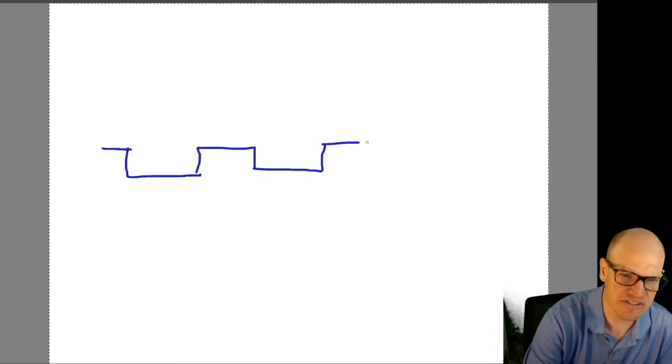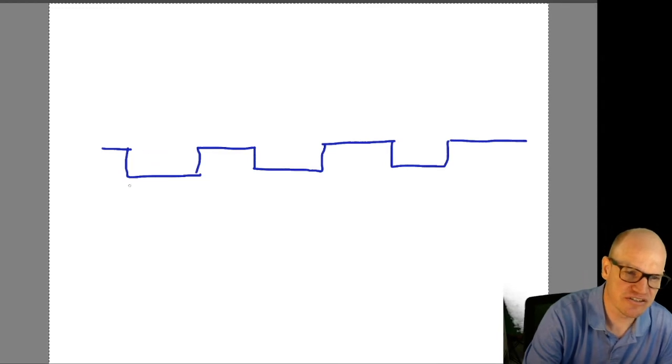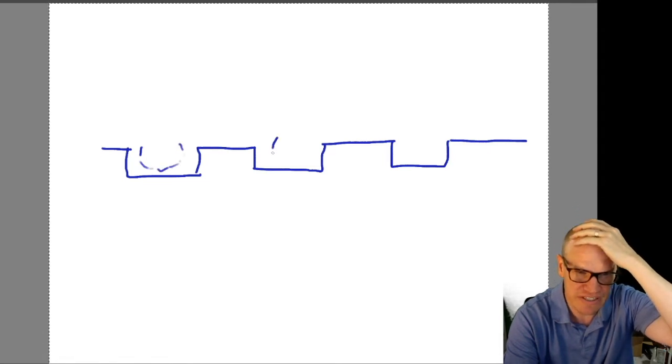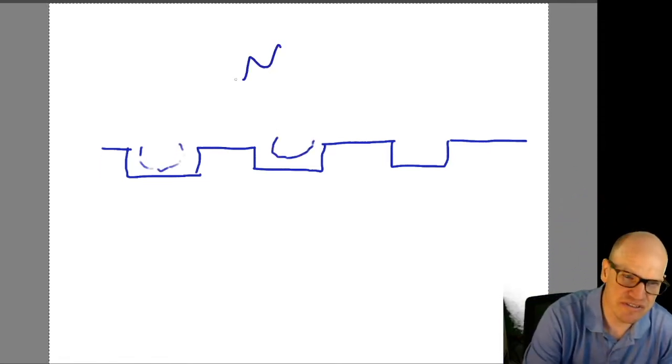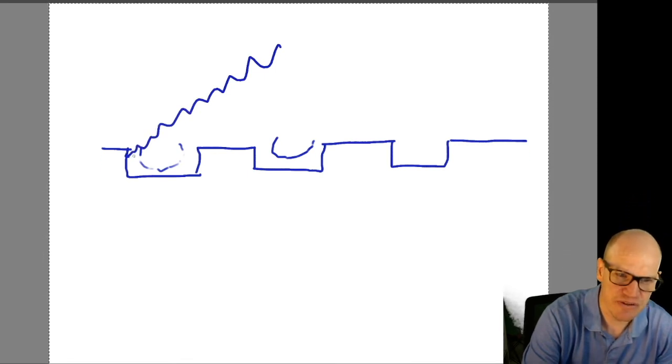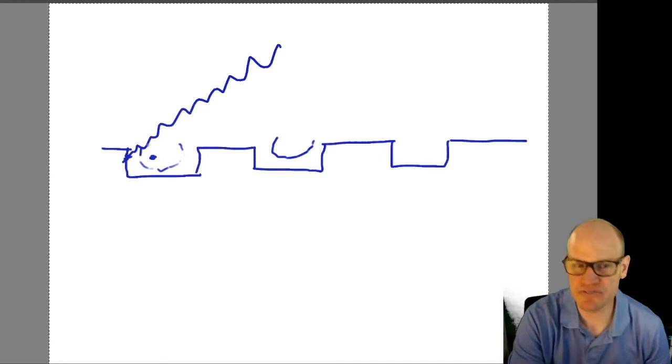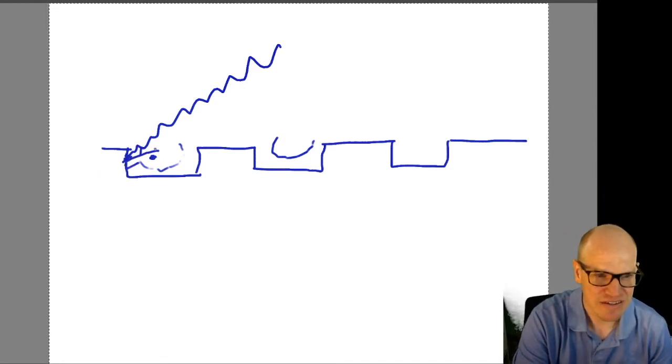So let's suppose that you wanted to make a digital camera. Digital cameras work off of quantum mechanics. So if anyone's like, why do we ever study quantum mechanics? You can say, well, digital cameras, man. So here is a digital camera. It's got these pixels, arranged in such fashion like this. There's a little electromagnetic field that will trap any electrons in these pixels. So light comes in, hits the surface of this pixel, so we're zooming in on the pixel. Light hits the surface and will dislodge an electron, and that electron will get trapped in this well. If you have lots of light coming in, you'll dislodge many electrons, and so you have a whole set of electrons like this.